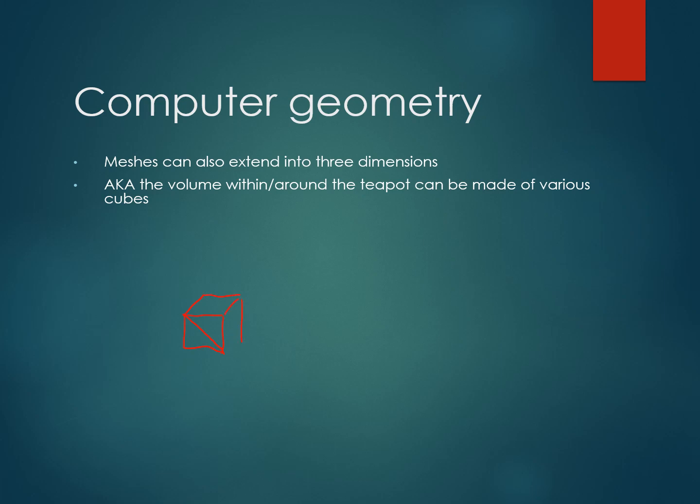So we effectively turn these into cubes, and these cubes then form the basis of our cells, as we call them in the simulation, where each volume element will have temperature and pressure and velocity data associated with it. And we build out these surface two-dimensional files, we fill them with a bunch of these 3D cubes, and that becomes the starting point for our simulations.